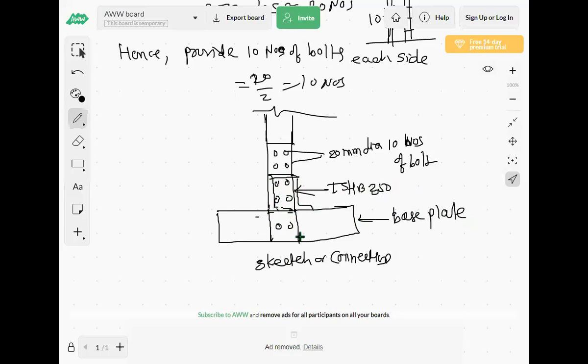Good. So here this side on this plate also. So in this way, the angle width is 115, and the angle depth is 150. So I have drawn this in the side elevation. If we draw in 3D, then you will get it. We have seen the 3D sketch in the design procedure. Are you getting? So in this way, you can design the bolted connection.